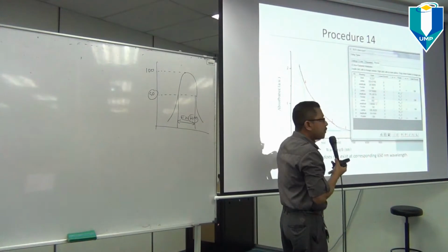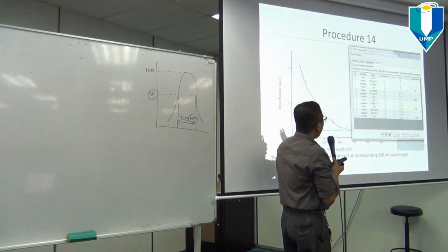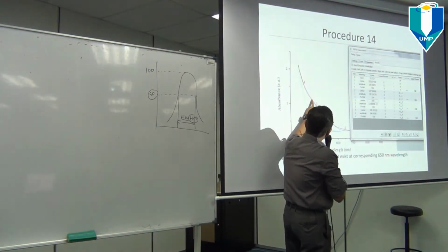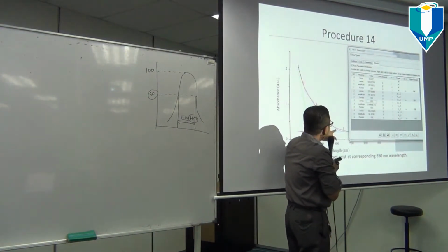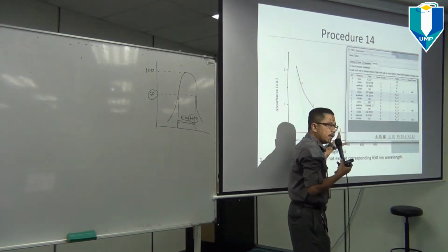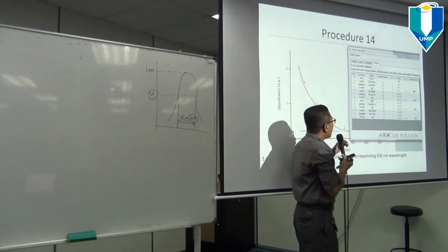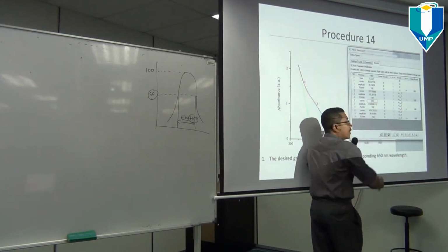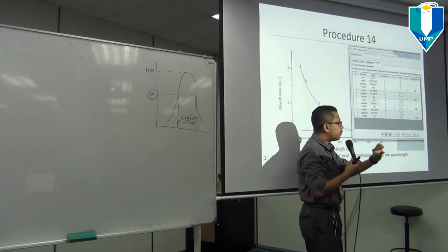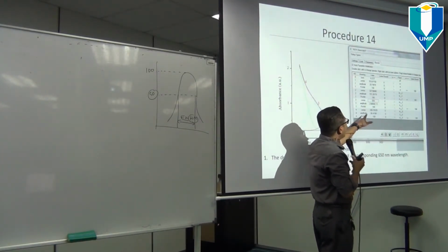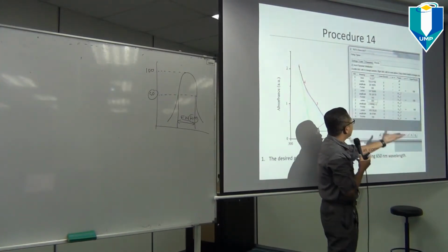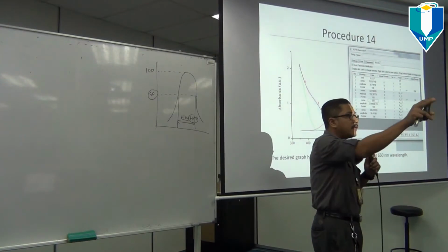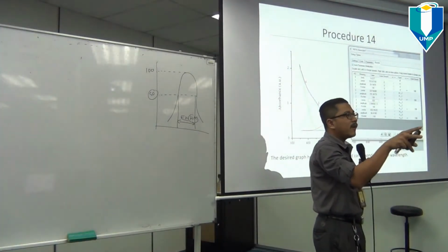Okay, they are all in the region of the data. But how about if the centers are correct, however the purple graph and the black graph still don't coincide over here? So the next stage, what you need to do is look at the amplitude. See this one? The amplitude is 10 to the power of -12, which is super small. You need to modify this, increase it, to become 80 or 60 or 20. But your graphs are okay. Do not modify your graph.